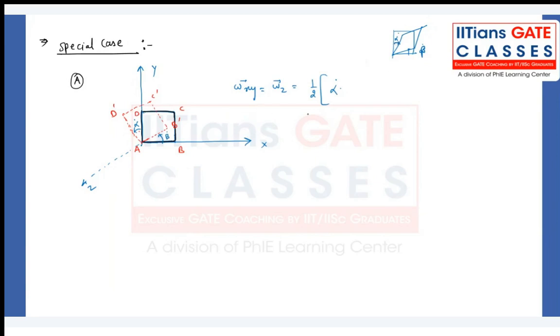That is negative, and anti-clockwise rotations I have taken positive, right? So here alpha dot and beta dot, both will be positive, and both are equal, and they are rotating in the same sense.